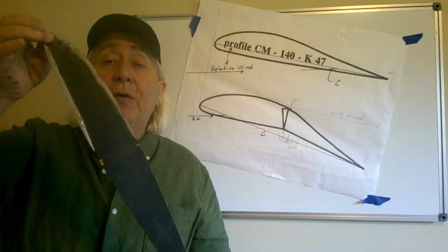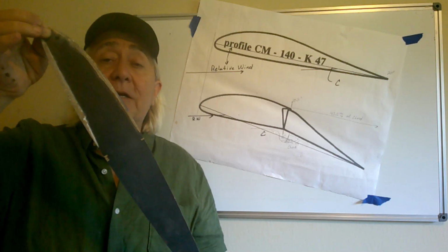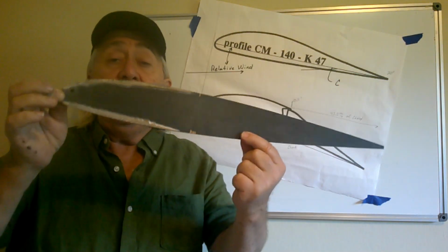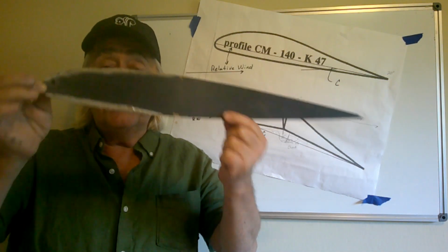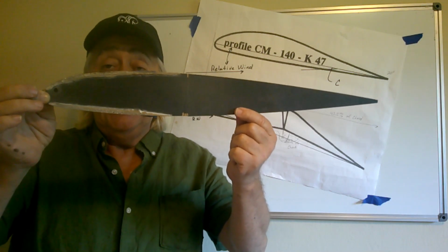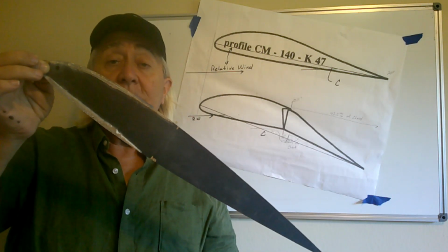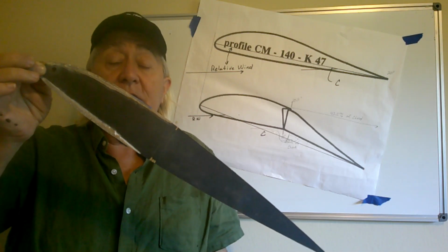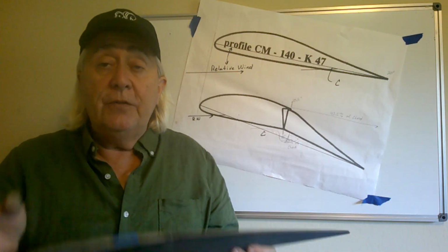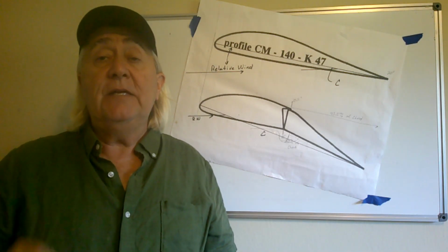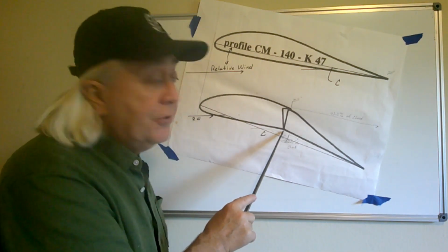Well, there, I'm putting the whole airfoil up at a higher angle of attack. So if the angle of attack for stall on this airfoil is 16 degrees, and I deploy my flap 20 degrees, I've stalled the airfoil. It's that simple. That's why the root cause of this accident is the location of the hinge point.